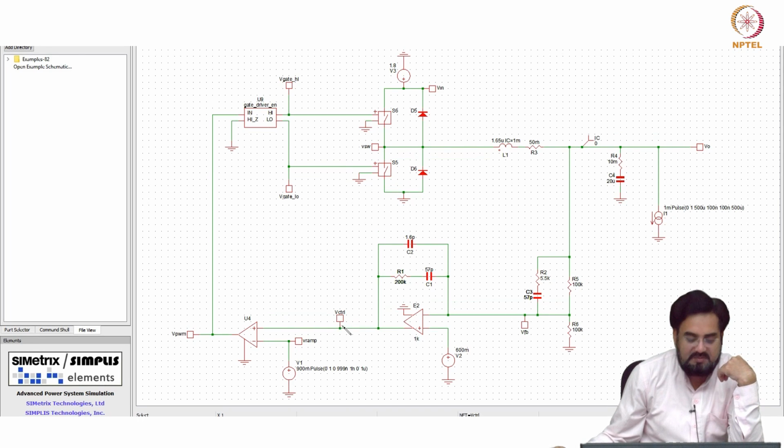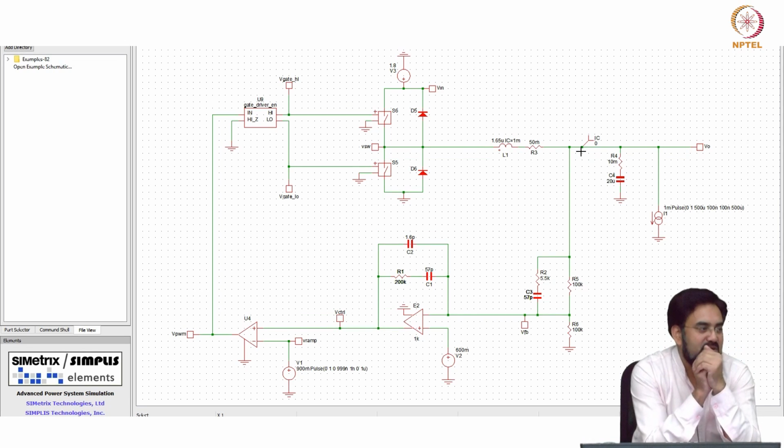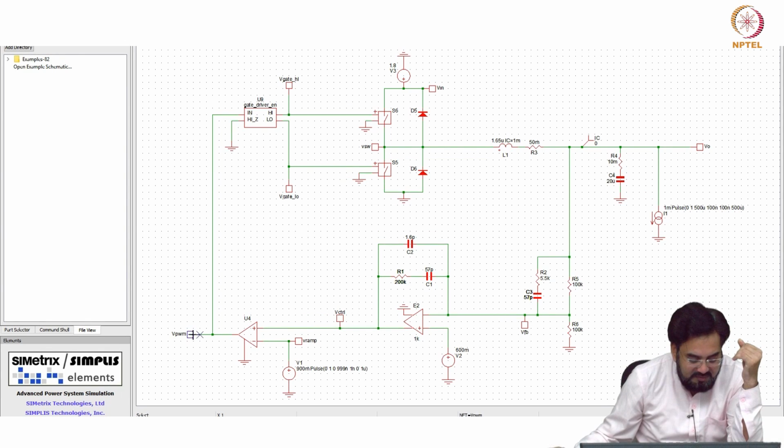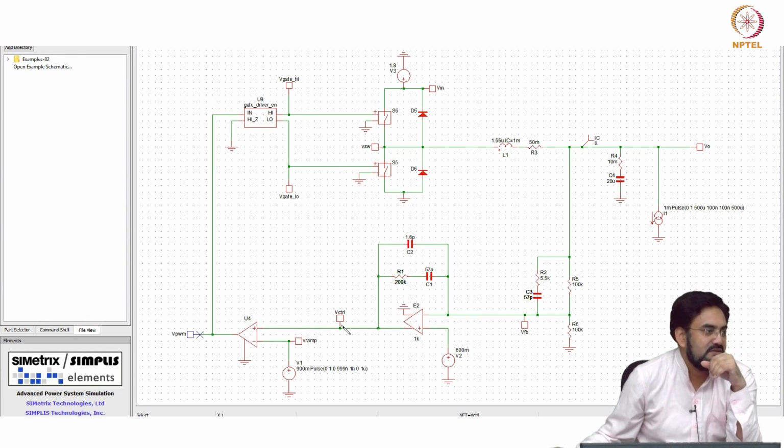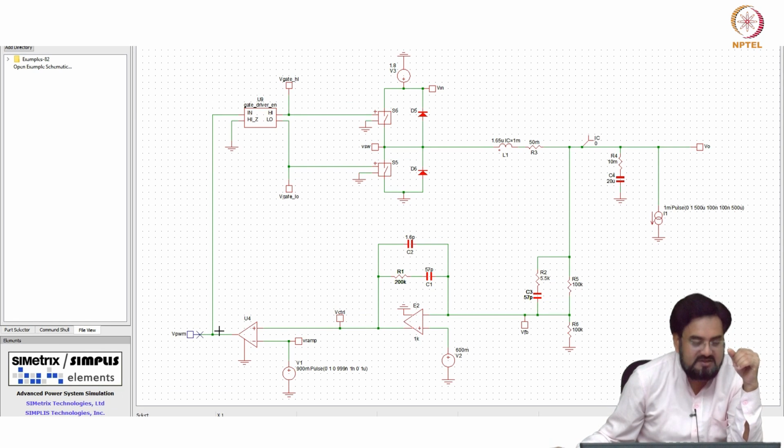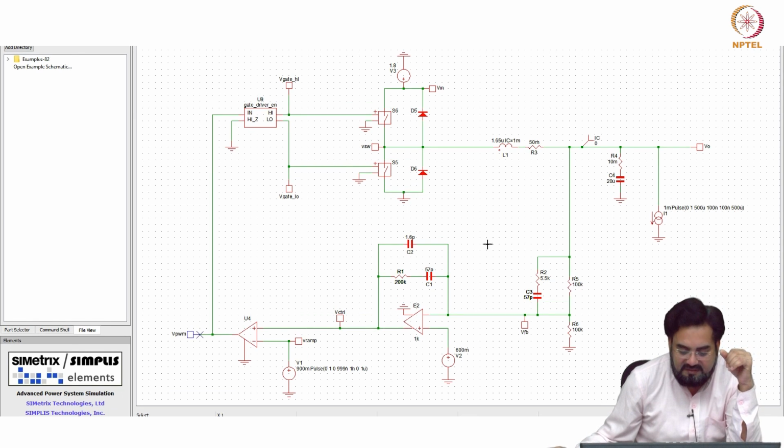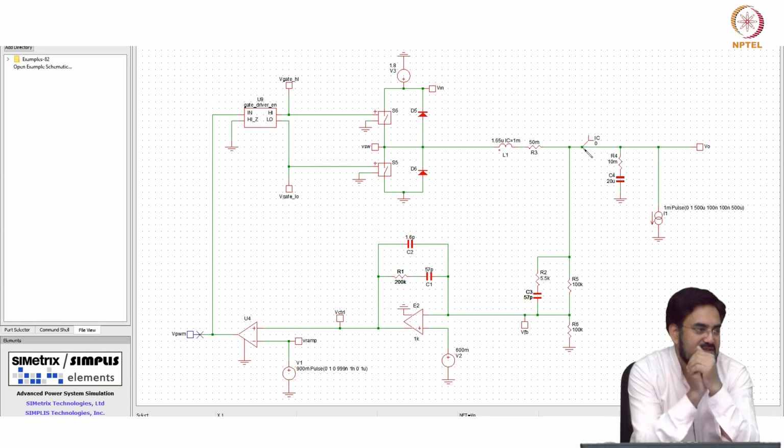If this ripple is crossing at the same point every cycle, your duty cycle will not change, your switching frequency is the same. So why would that affect your output ripple? It should not. VPWM is not changing due to this. Then if VPWM is not changing, why would any change happen in the power stage or output voltage? It should not happen. So why do I care about this?